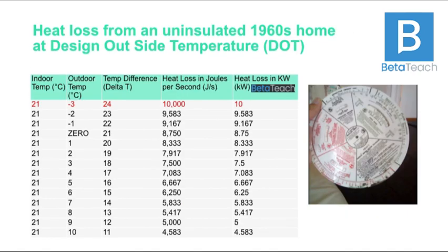So we used to do heat loss calculations. Engineers haven't been doing them, and that's not their fault. It's because we had an industry that liked people to put boilers on the wall, and then the combi boiler came around. We needed a high powered boiler, because the combi boiler is actually a centralized instantaneous hot water heater, so you need a lot of power in it so the hot taps run hot.